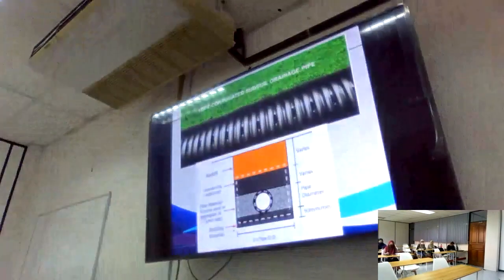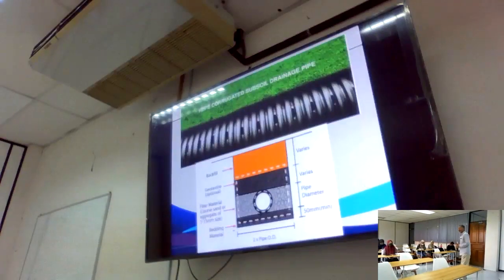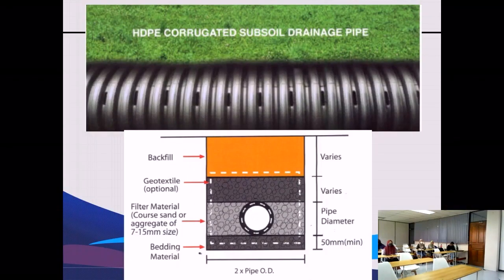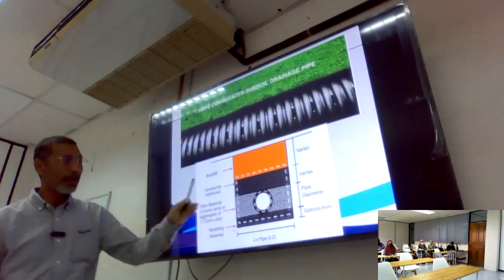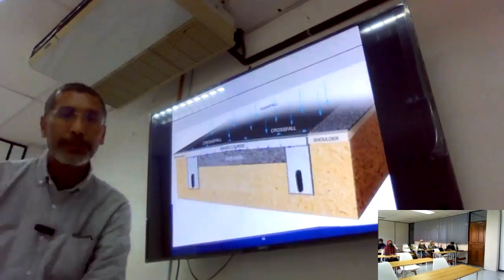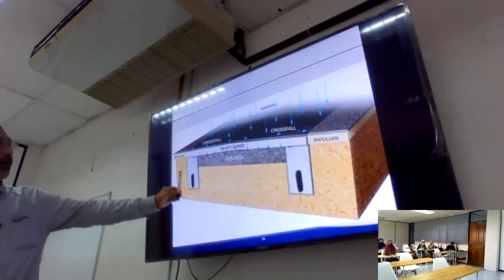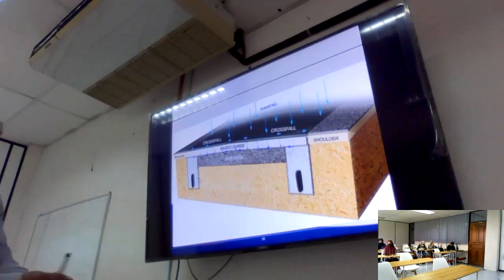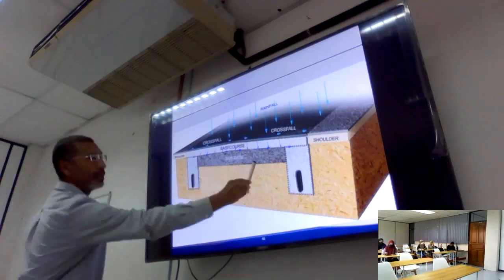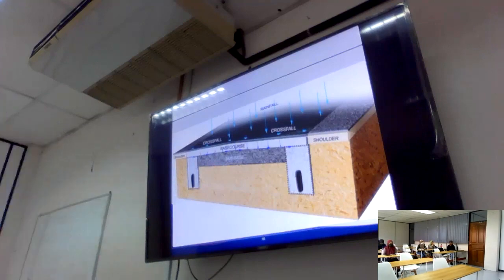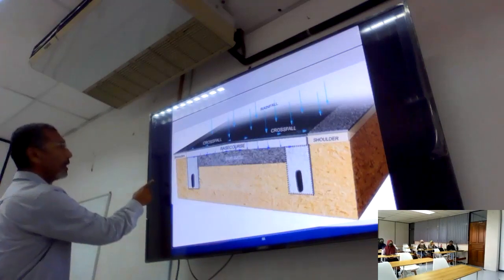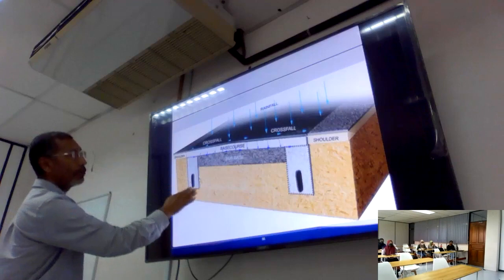Okay, just now I mentioned about subsoil drain. So this is a typical subsoil drain that is below the ground. The subsoil drain can be concrete or poly pipe like this. Usually they are installed like this below the ground. And for road, they will be placed at the edge of the road, because we don't want water to come below here. You want to catch all water. You don't want water to come nearer to the surface, because that will weaken the subgrade. Okay, we want to protect the subgrade. So whenever there's water coming, it will be cut here. It will not go up here. Right?